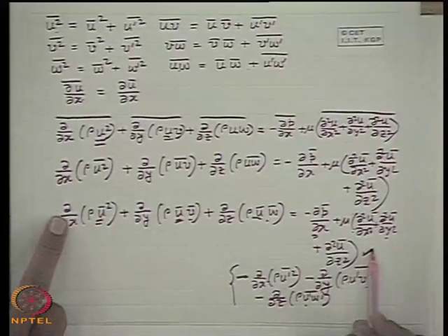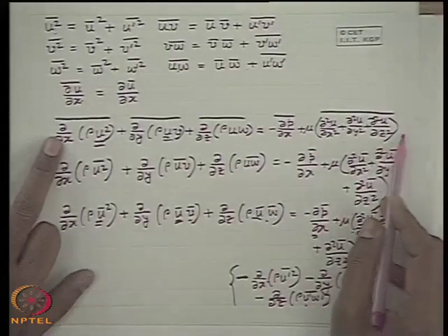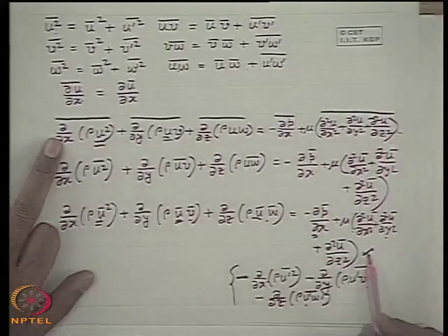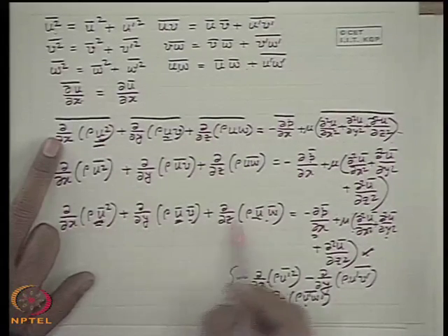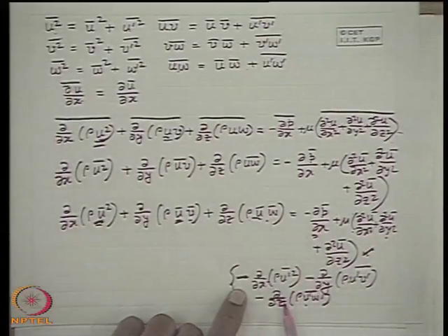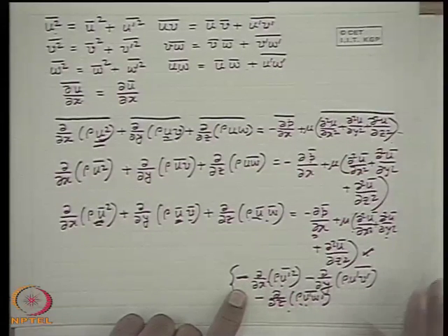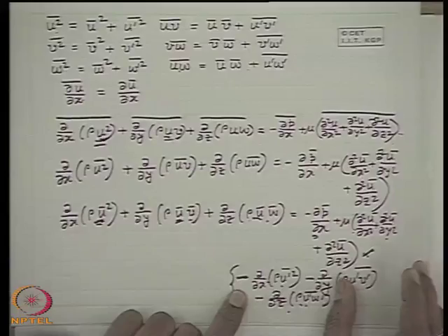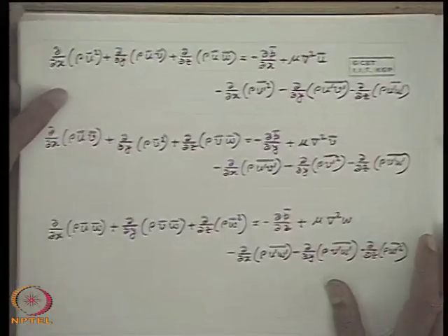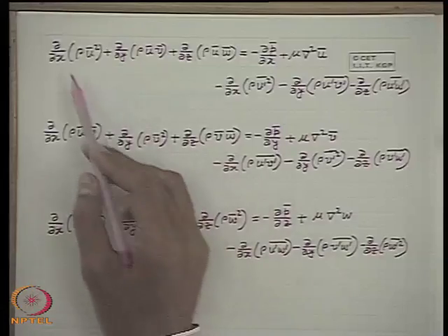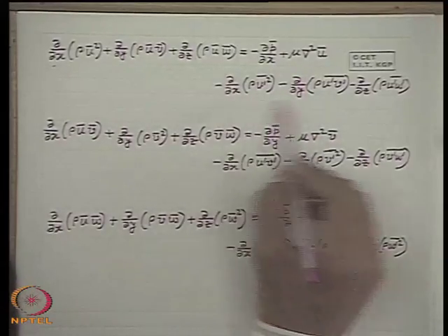That means, if we compare up to these equations with the equation without taking the time average, they are same. Only the velocity components are replaced by their time average values plus some added quantities or added three terms, which are the terms containing the fluctuating average values of the fluctuating component. So, if this way we perform the modifications for three equations in three directions, we get this thing. This we have derived earlier.